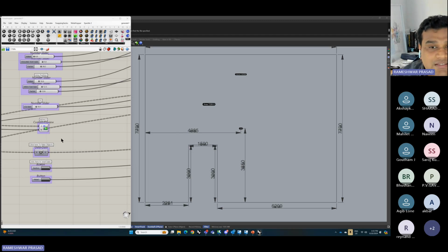So the biggest roadblock in previous years of exporting models directly from Tekla to STAAD or STAAD to Tekla was that in STAAD everything was modeled center to center, whereas in Tekla it is generally top of steel or top of concrete, right? Now, because of the Grasshopper plugins released by Tekla and by Geometry Gym and so on, you can stick to center modeling in SAP2000, and then you use the same model but make a few changes using the Tekla native plugins, and it automatically generates a TOS model. So that's why you don't have to do it twice.